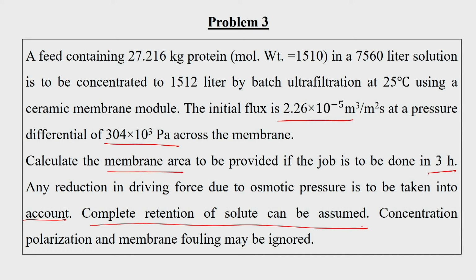So, we can say this one RR will be 1. So, Cp can be 0. Concentration polarization and membrane fouling may be ignored. In that case we can say concentration polarization is not taking place, or that membrane fouling is not significant. Okay. So, now we will be solving this problem.